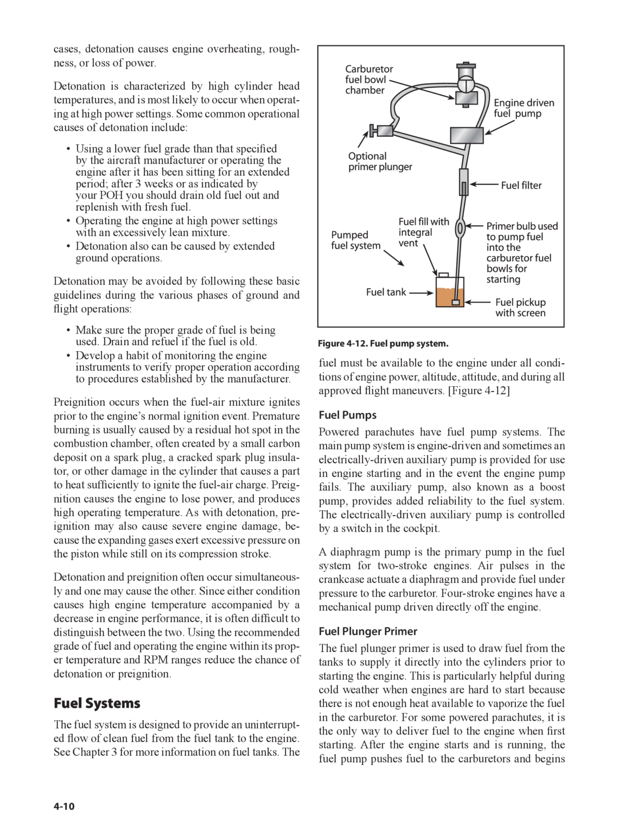Operating the engine at high power settings with an excessively lean mixture. Detonation also can be caused by extended ground operations. Detonation may be avoided by following these basic guidelines during the various phases of ground and flight operations.